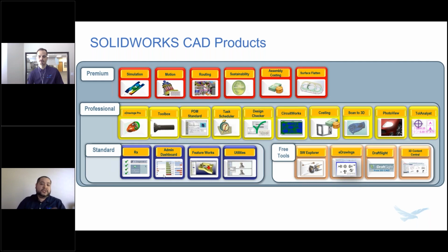So very similar to what I showed you in SimXpress, but it unlocks a variety of different tools, like the types of loads, how you can mesh it, and how it can be restrained. So if you have that option, definitely take advantage of that. But if you have SolidWorks Professional or SolidWorks Standard, notice that we don't have an analysis type option here. It's part of just the free utilities like what we just saw today.